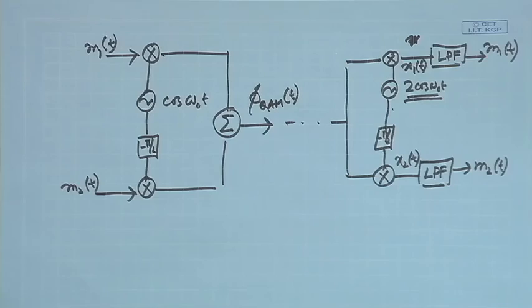Something is coming already with the carrier because it is modulated. So, that same carrier I have to somehow extract, so that the phase and frequency are completely synchronous with the incoming carrier, and then with that local oscillator generating a synchronous phase and frequency carrier, I have to demodulate it. Whatever we have seen so far, amplitude modulation was probably the non-coherent one, where I can employ non-coherent demodulation. VSB-SC definitely requires a coherent demodulation, because I have to multiply by the carrier. SSB also, if I do not put a carrier, requires a coherent demodulation, and for VSB also we have seen that it requires a coherent demodulation. This one definitely I can see already requires a coherent demodulation.